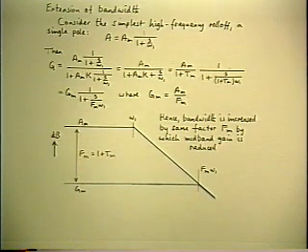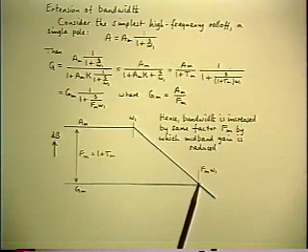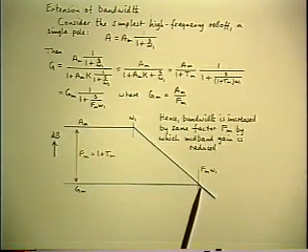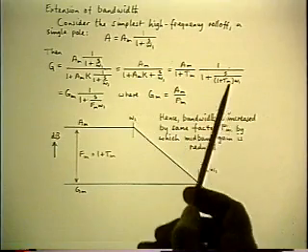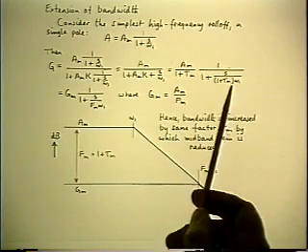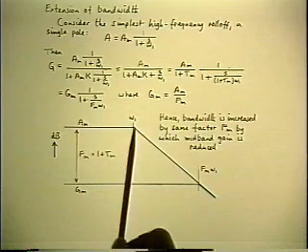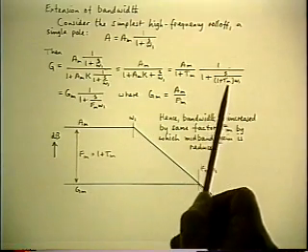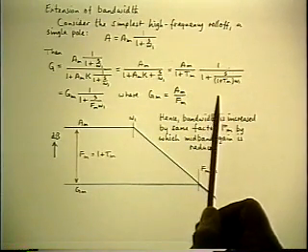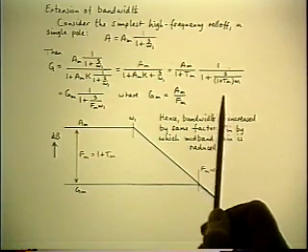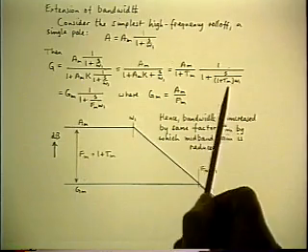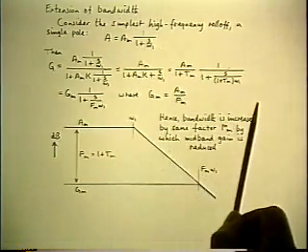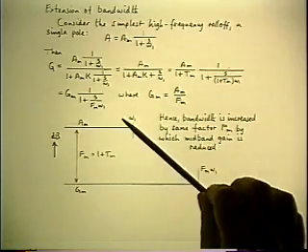But the important result of this picture is that the pole of the closed loop gain lies on the same asymptote as the pole of the open loop gain. Because the algebra shows that the relationship between the two flat gains and the two corner frequencies satisfies the gain bandwidth trade-off. It's the same ratio. Because the ratio of the midband gains is FM, so is the ratio of the two poles. Therefore, the two poles lie on the same asymptote.